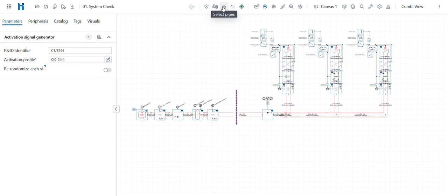The first four calculation steps that we have seen are full load design calculation steps. The last calculation step, simulation, is going to take into account the dynamic partial load behavior of our system, which will be influenced by the exterior air temperatures of our system. So what's very important is that for this step, all of the controls also need to be implemented.